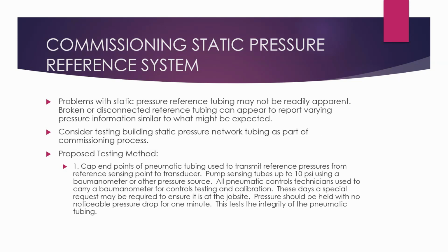So, commissioning of this static pressure reference system. A static pressure reference is a good candidate for commissioning because the problems with the reference aren't readily apparent. A broken or disconnected reference tubing can appear to report varying pressure information similar to what might be expected. And we had this in one of our buildings.